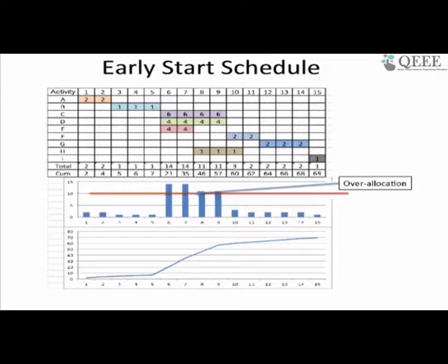One says late start of D, that's correct. The other says resource leveling. Can you explain? This is what resource leveling is in a very basic sense. We had a very high peak level of 14 resources. It is over allocated. In one way, this is resource leveling. I will also explain other forms of resource leveling, not in great detail, but this is the most basic way.